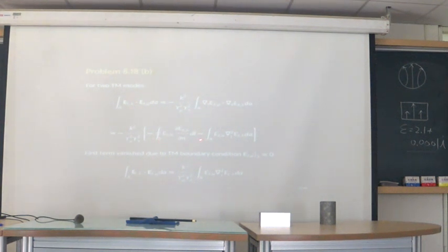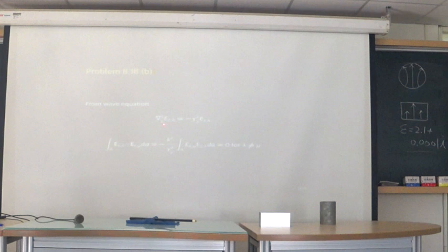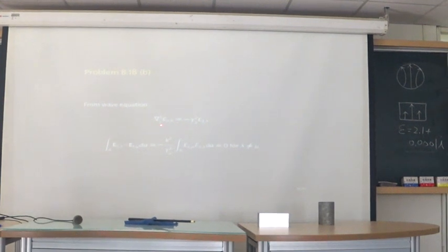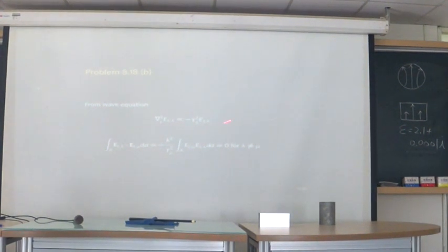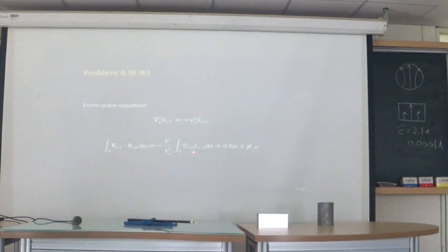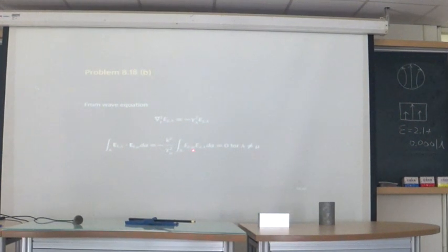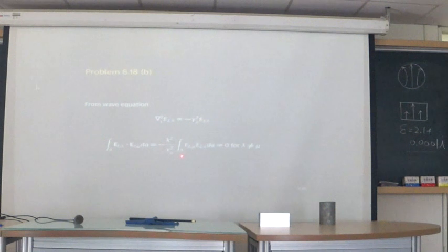So we only have the second term, and the second term has a Laplacian of Ez here, but since the Ez satisfies the wave equation, we can replace the Laplacian of Ez with gamma lambda square. After this calculation, we can find that the transverse fields' inner product integrated will equal the integration of the Ez fields. And this integration is calculated in problem A, so we know that it is orthogonal for all TM modes.